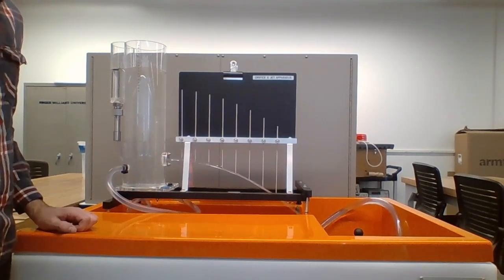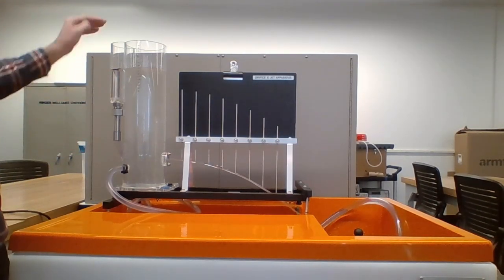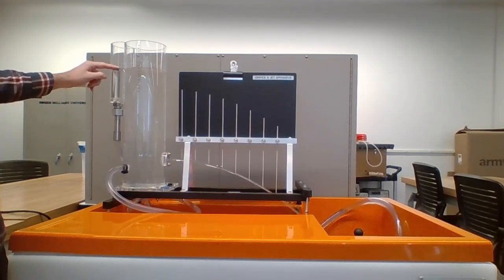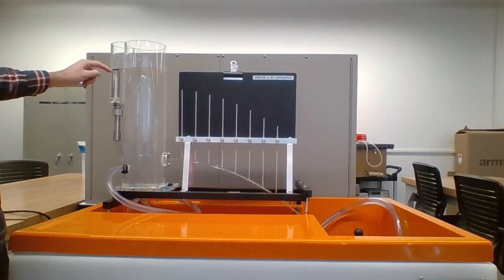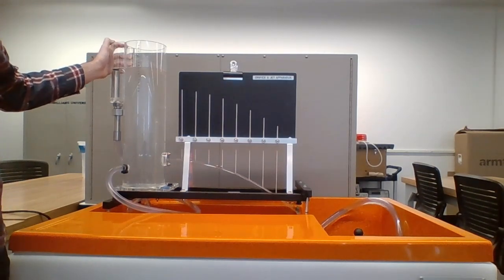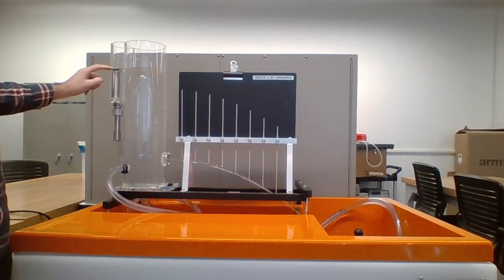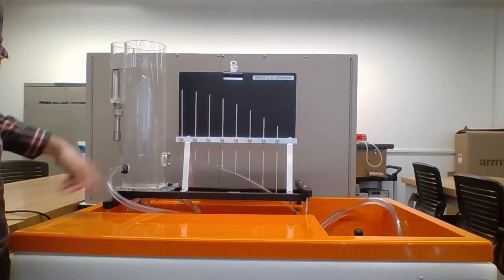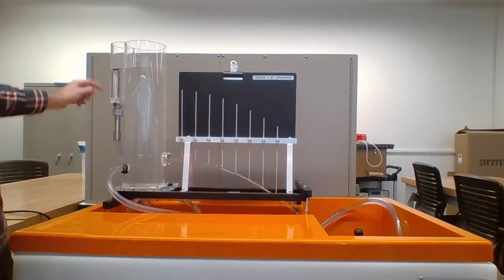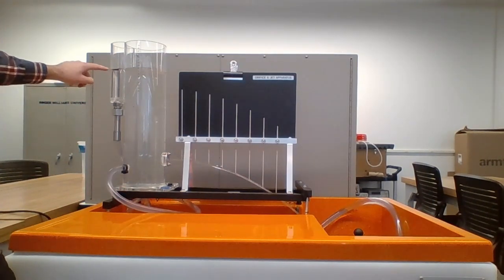So there's a bit of a balance between having too much and not enough flow rate. If you have too much flow rate from the pump, the level will maybe overflow. Actually, this pump has enough flow rate to overflow the tank. And if there's not enough, then of course the orifice drain will be larger than the pump inlet flow rate. But this is pretty good right here. So we're relatively stable right above the outlet.